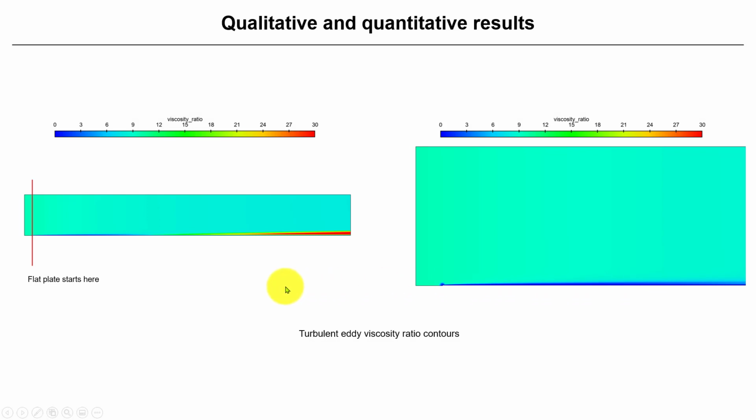If we go forward, now we have the eddy viscosity ratio, which is a very important quantity. Probably people ignore this one, but it tells a lot about what you are doing, and it's also a good guideline to check if you have a good mesh. Remember that when we looked at the budget of turbulent kinetic energy, it peaks in the buffer layer, in the boundary layer.